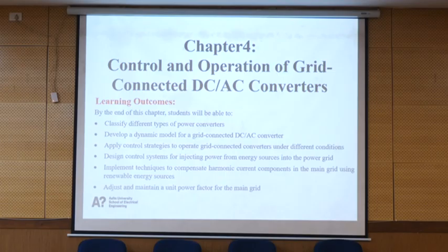You mean from the grid connected to islanding mode? So we have this static transfer switching, STS, static transfer switching. So it detects the voltage and frequency of the system, the network. And if we pass this limitation, the border of the limitation, it means that we have the problem in the grid. So for example, if short circuit happening, we have the voltage drop, and you can see that there are some problems. So it is better that we get disconnected, otherwise our load will be damaged.